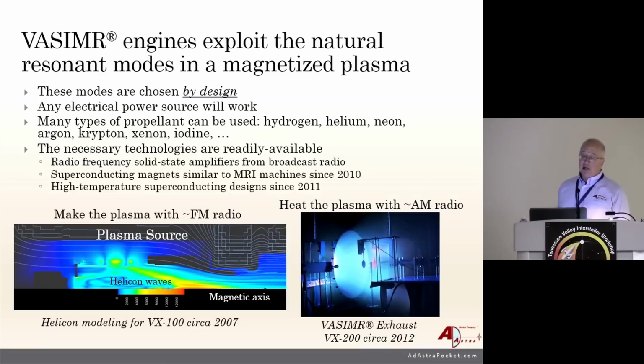We do use superconducting magnets. We've been using them since 2010. It's similar to the MRI magnets that you see in hospitals. It's just under 2 Tesla maximum field, and it is conduction cooled. It doesn't have liquid helium sloshing around it. It actually has cold heads that attach and conductively pull the heat out, which is an important technology for space. You really don't want liquid helium running around loose in your system.